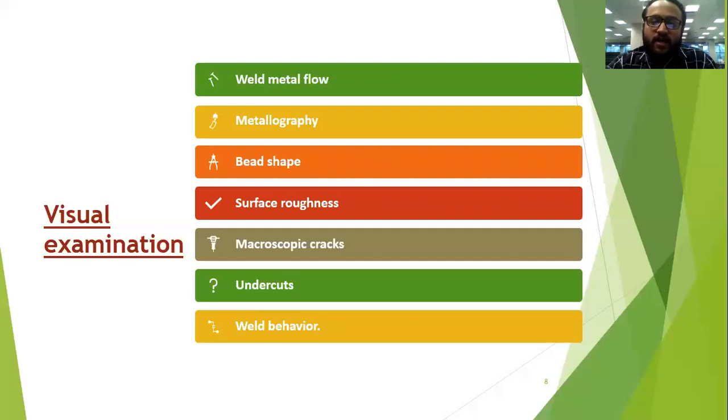And some visual examination was done when I ran the experiment. Some of the important visual examinations were weld metal flow, metallography, how the bead shape is, how the microscopic cracks are, and how the weld behaves.